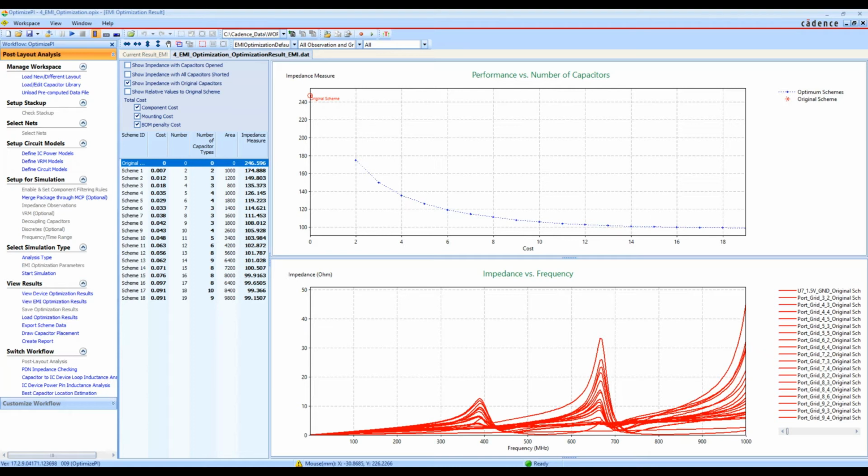Roger nicely described how a decoupling capacitor is used, and in this case, if we put 2 of them on our board, it'll tell you which value they need to be and where they go in the report that you can get from this. But we're using one, you can see in the tech tip there, one 100 nanofarad cap and one 10 nanofarad cap, and we're putting those on our board, and it'll tell you exactly where to place them. And you can see that that's starting to push our resonances out.